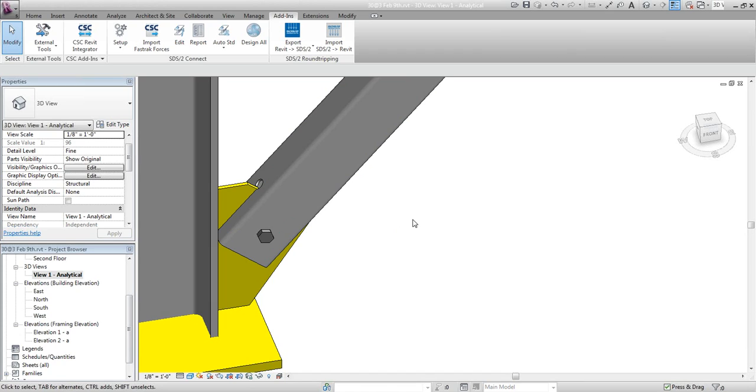A lot of fabricators want that hole in there so that when they run this through their CNC machine, it'll just drill a hole in there, and then they can go ahead and manually cut out the rest of that notch there. Makes it a little easier for them if they don't have a machine that is capable of doing that whole notch there.